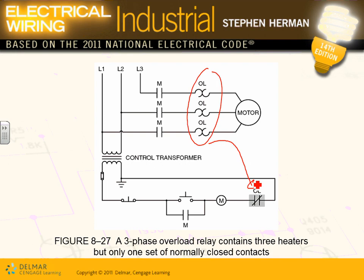So this one that you're looking at right here, guys, is actually heaters, and that's how they open the overload. If the motor, like I said, is 100 amp, and you're pulling 129 amps out of one of these, it will sense that and create heat. The heat will melt certain material. When it melts, depending on the design, it will push 2 contacts open.